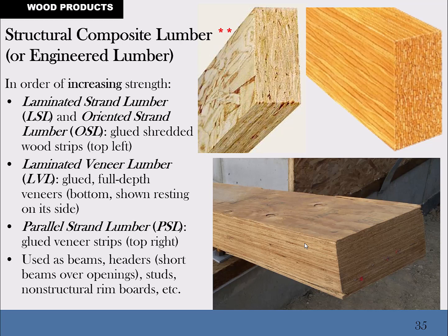For years and years, LVL and PSL, laminated veneer lumber and this twig-based thing called parallel strand lumber, or PSL, have been competing with each other, and they still kind of do, but I think parallel strand lumber will win the day, and it's already starting to. The economics are in its favor. But I tell you, it's some heavy lumber, because there's a lot of glue needed to glue all those twigs together, and glue is heavier than wood.